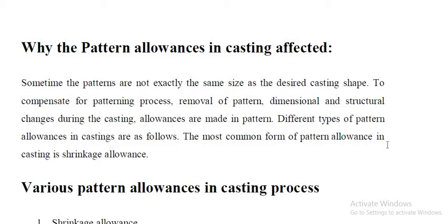So to remove that discrepancy of the shrinkage, what we do actually is we make the pattern into a larger size so that the discrepancy of the shrinkage will be removed.